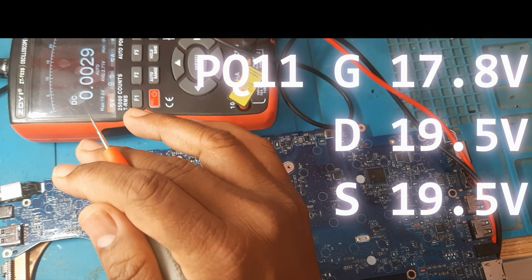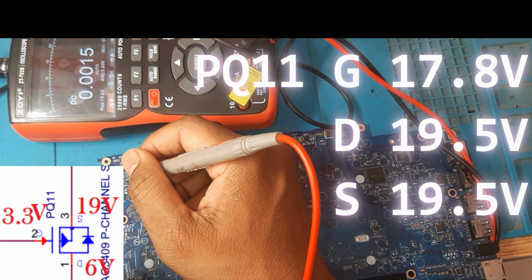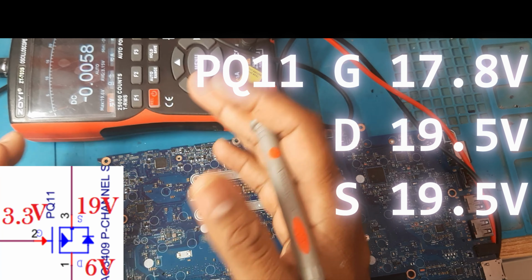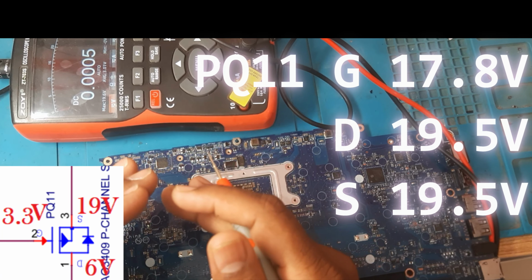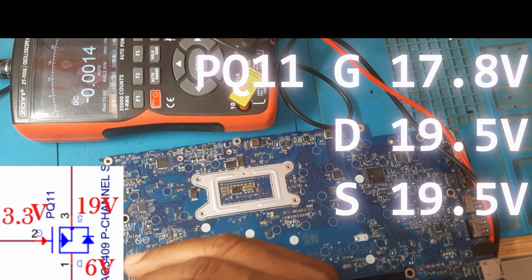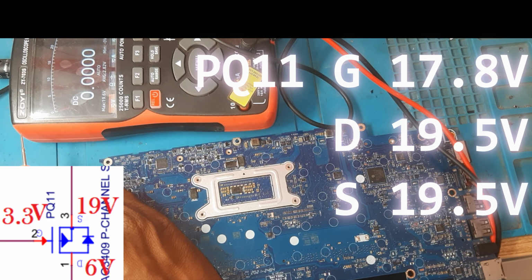See, the main problem is here because the gate has voltage, correct? If the gate has voltage, the source and drain should be separate. Here the drain is also 19.5 and the source is also 19.5. Something is malfunctioning here, correct? It should not be equal. The voltage divider should happen, otherwise approximately 17 or 18 should be at the drain, but as per the source only we are getting. In this case, in a cold test only we need to check all the components.